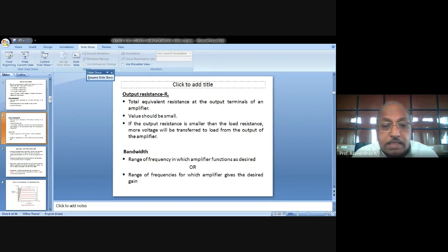That you have to understand very well. What is this inverted amplified version? I told you that for faithful amplification, whatever changes occur on the input signal, the same kind of changes should be made available at the output signal also.